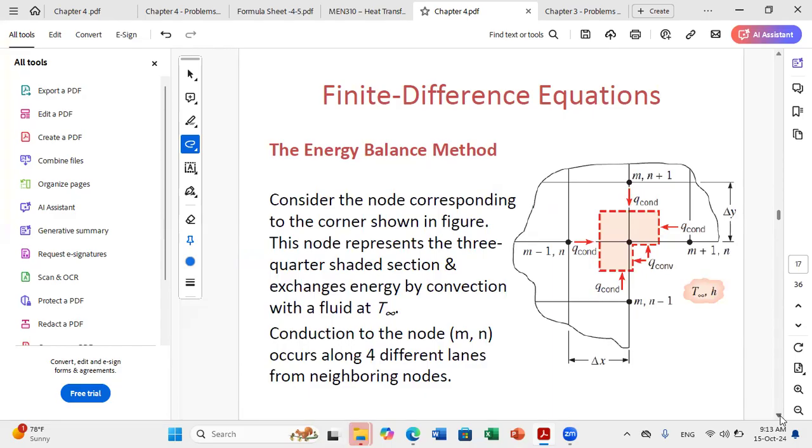Now, what is challenging here is not cells at the center, it's cells at extreme points, at extreme surfaces. And we'll discuss this together next time: what to do with a cell that is exposed to the surroundings. Here we should use the boundary conditions appropriately, because whenever you have a cell having a node at the free surface, you need to use the boundary condition appropriately in order to write the equation for it. So we will tackle this idea next time.